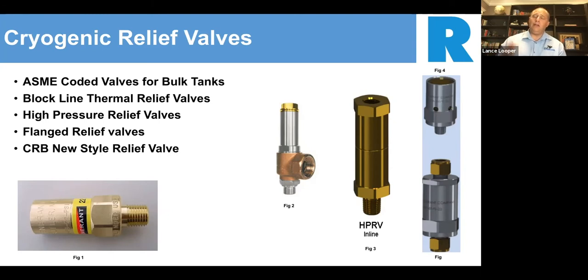Back about 8 years ago, most of the pressure relief valves that we had on our liquid cylinders were just a standard thermal style relief valve. What you get with that is what I call the shotgun effect. The easiest way to describe it is a call I got one time from Matheson Trigas, saying that a little old lady was concerned that people were shooting at their liquid cylinder on the side of the road. I can understand why she would say that, because back in the day, when a lot of these valves went off, it sounded like a shotgun.